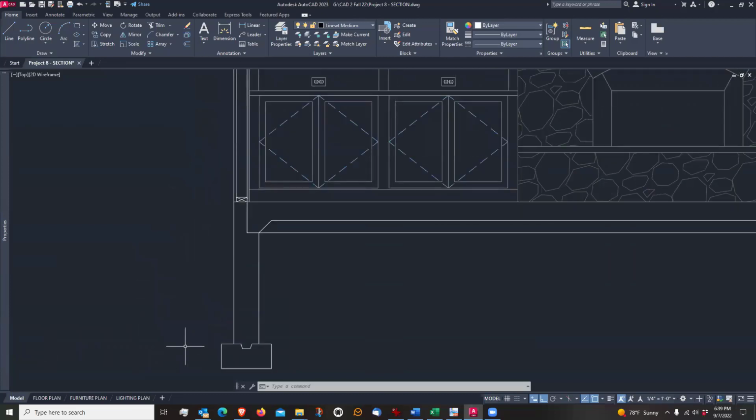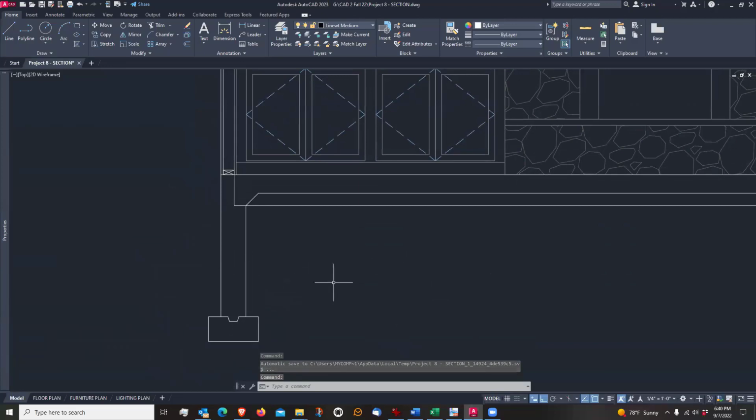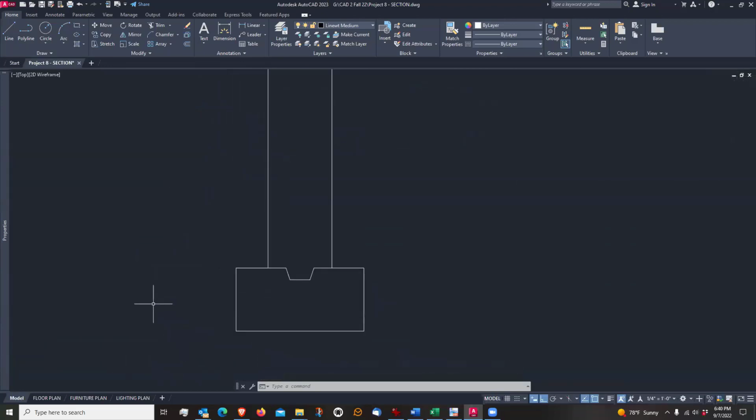The last thing we want is water to just sit by our foundation wall. Foundation walls have little cracks in them, and if you've got a basement down here, then you've got a flooded basement. So we want to put a drain tile here, and it's just going to be a 5-inch diameter drain tile.